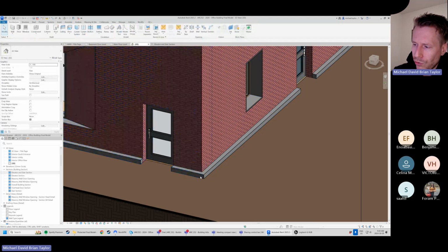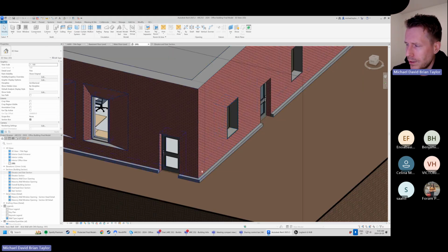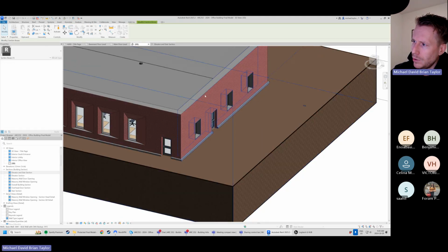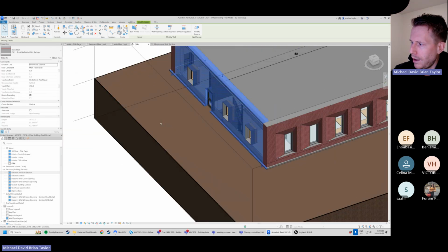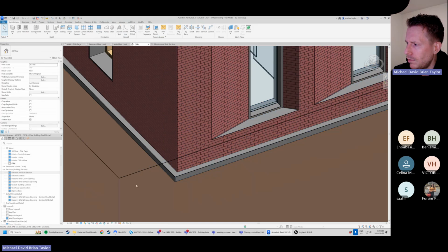So this can be really useful if you really want to do additional detail in your walls, things at the base, maybe some nice little architectural detail somebody wants to get across. A control joint is probably the most common one that I've used it for, so control joints in masonry systems. You have to change the profile, but get the idea. Just so you can see that now EW1 has this sweep around every time we've got a wall.